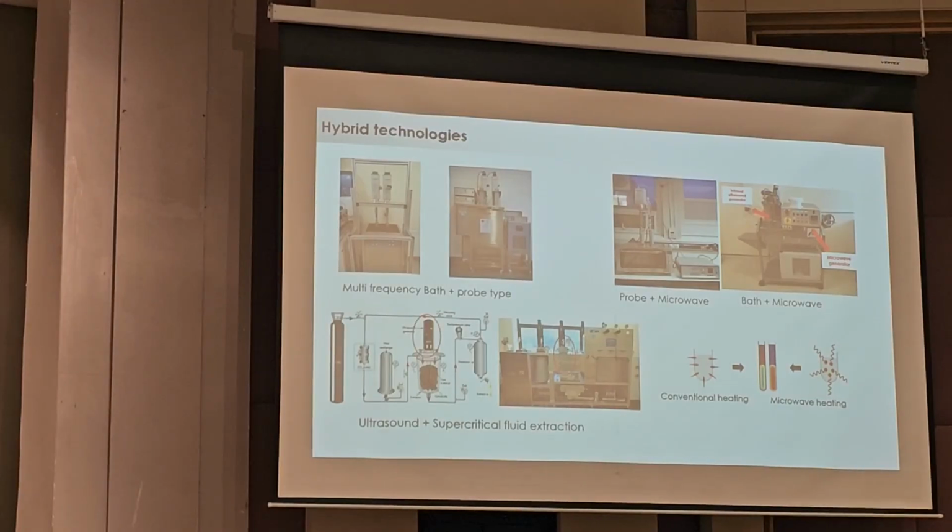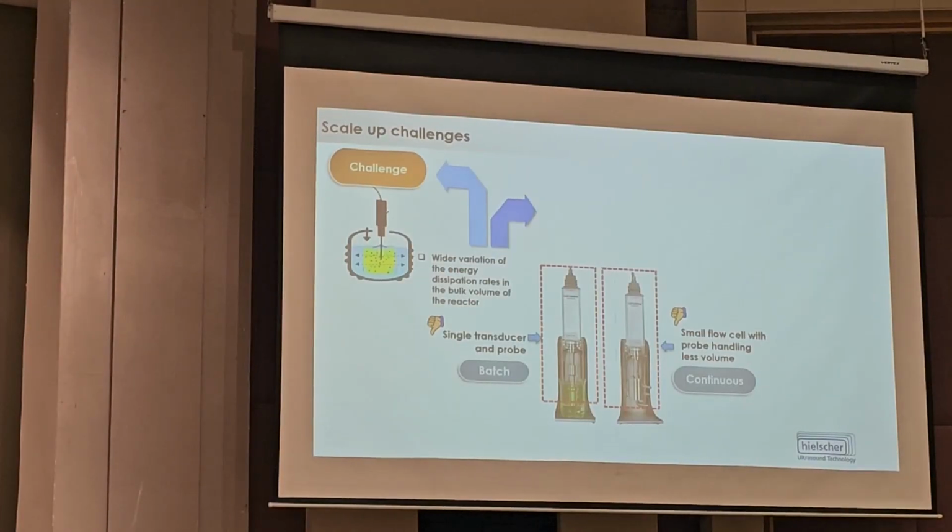important. Something like high pressure processing, we use 600 megapascals, but the literature says 900 megapascals. But if you go and see the material at 900 megapascals, after 100 cycles you have to relook into the vessel design. So these are some of the complications when it comes to further scale-up operations. So the majority of research stops here.